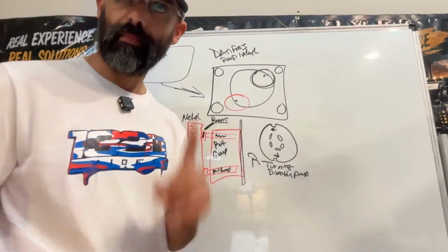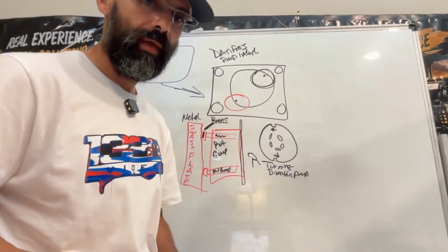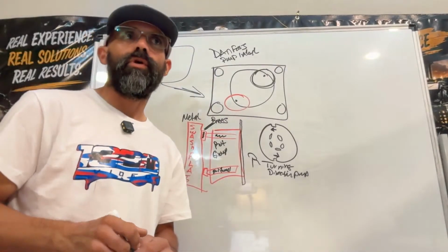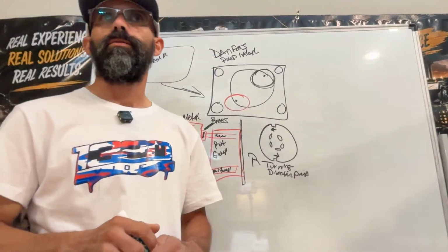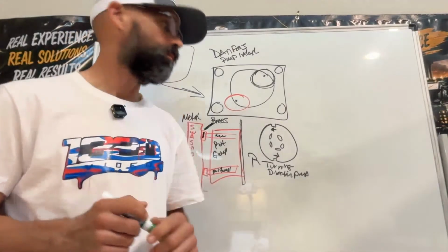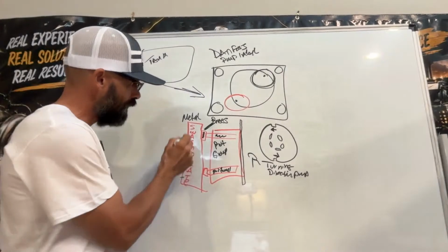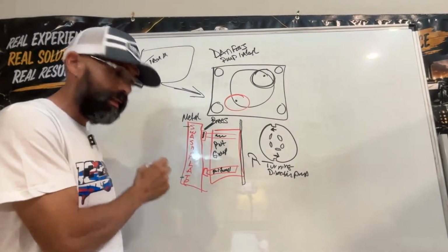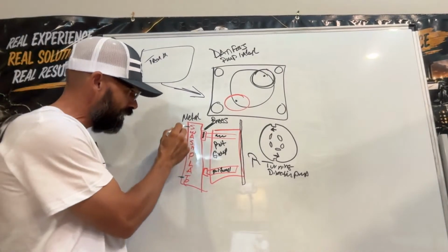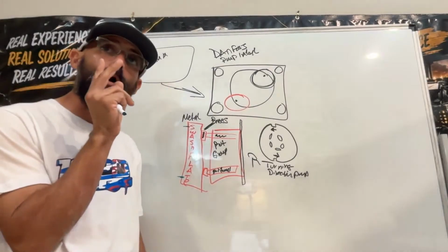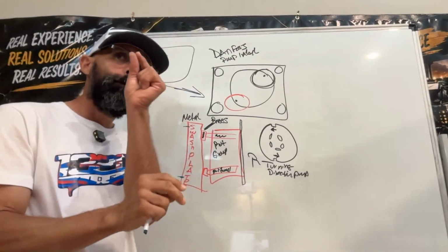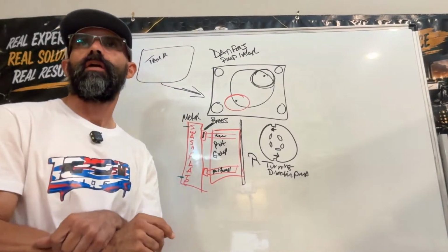Why do I say that? Not because you're trying to be Inspector Gadget or Sherlock Holmes. It's because the swash plate on the hydro pump has four puny holes for lubrication.